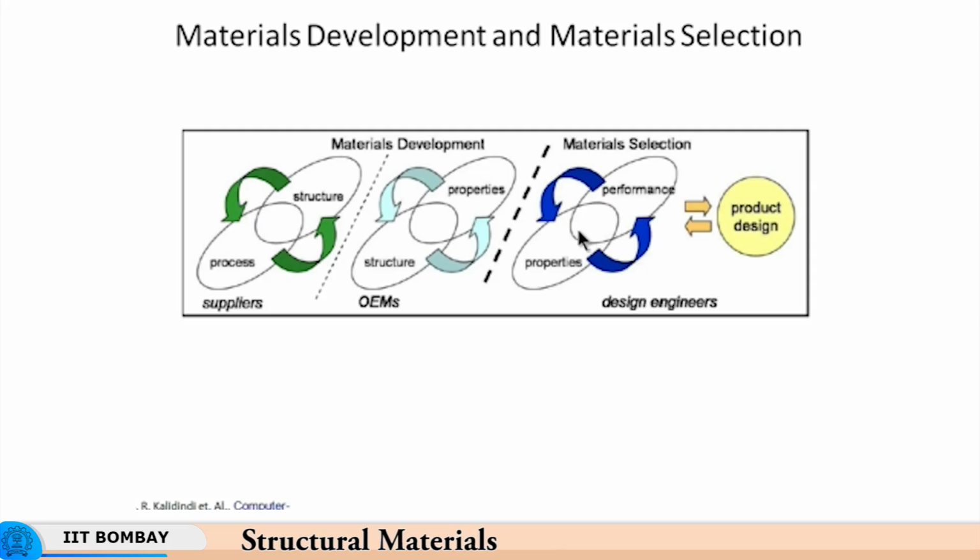So, there are certain requirements which translate into properties, and these properties can be achieved through the right kind of microstructure. So, you can plan for the microstructure and the crystallographic structure, and this structure has to be achieved using several processes. Now, these processes could be different manufacturing processes under room temperature conditions or high temperature conditions at different rates of straining, at different rates of deformation, or one can achieve it using a series of treatments like heat treatments, for instance.